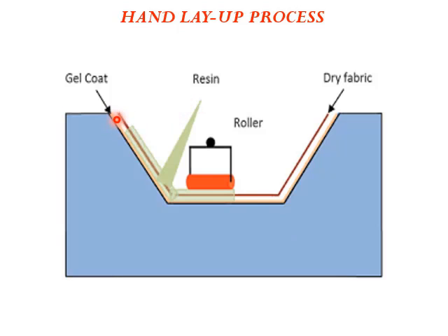Once the gel coat is applied uniformly over the mold surface, the next thing is pouring a resin. A uniform layer of resin is poured on the gel coat. Then above that we are going to place the fabrics, that is the reinforcement. It may be continuous, or in mat form, or in tape form, or in discontinuous forms also.